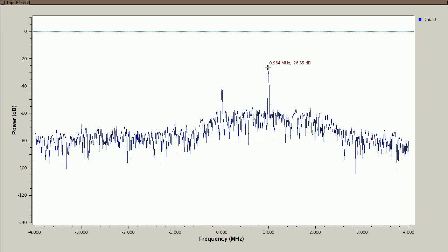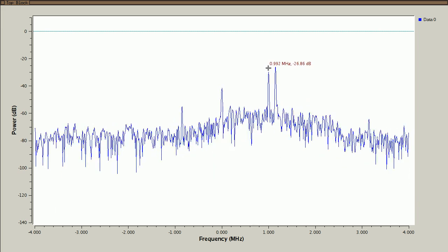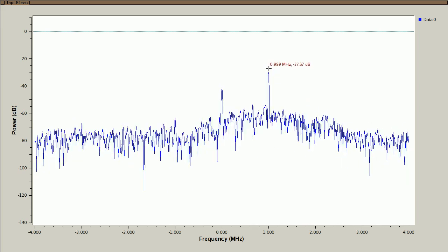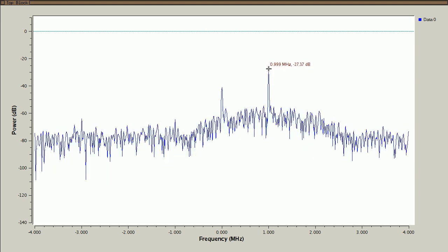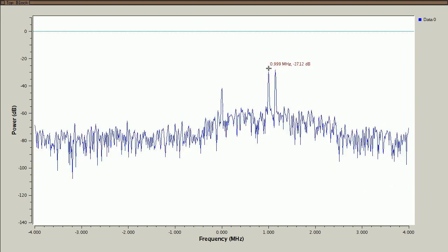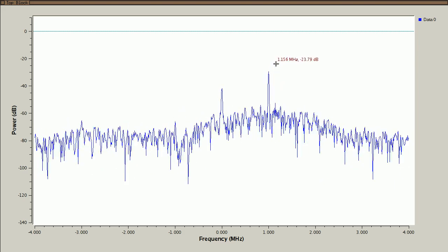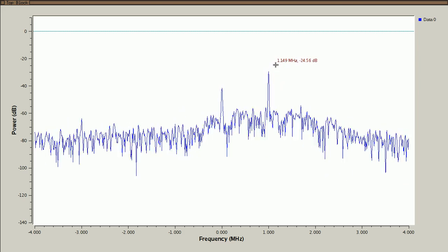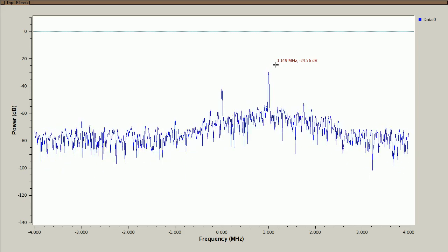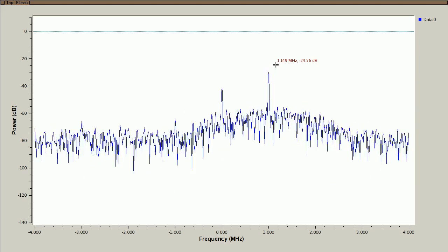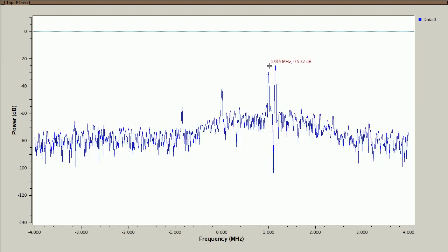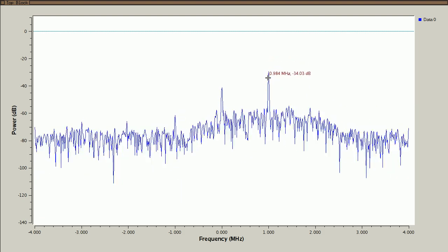That's actually the DC offset that was received by the HackRF in the first place, and now we're retransmitting that spike. That's not very good, is it? This signal up here, 150 kilohertz higher, is actually the signal that we're intending to transmit. And then this spike 150 kilohertz below it is something that we shouldn't really be transmitting.